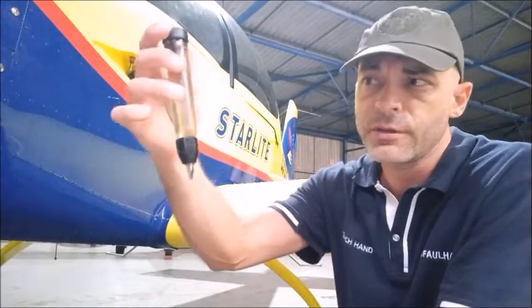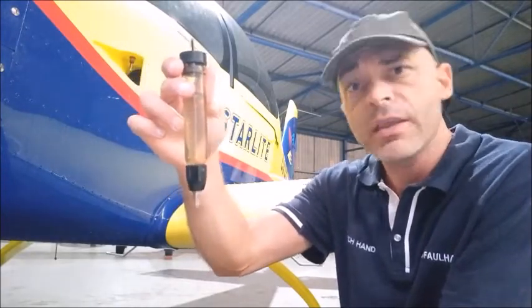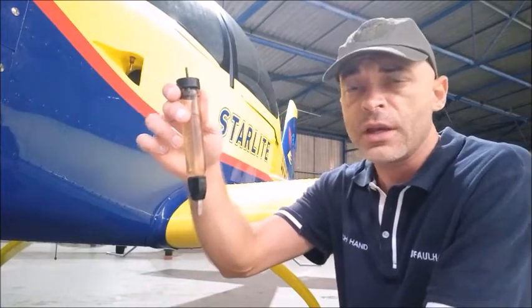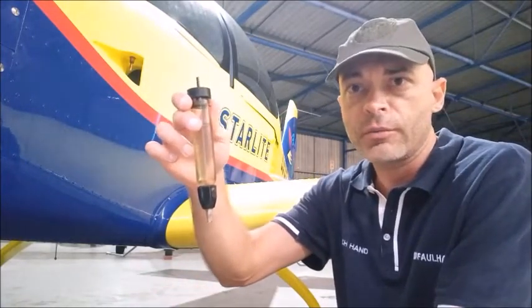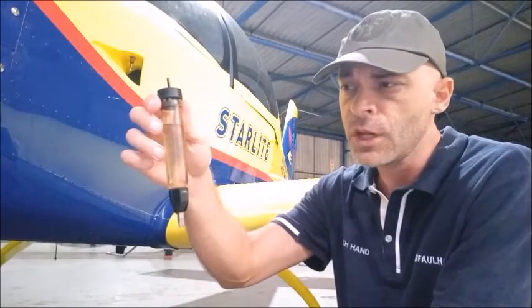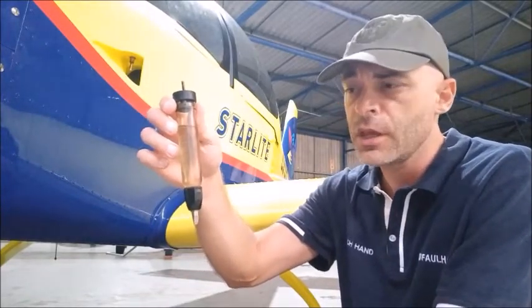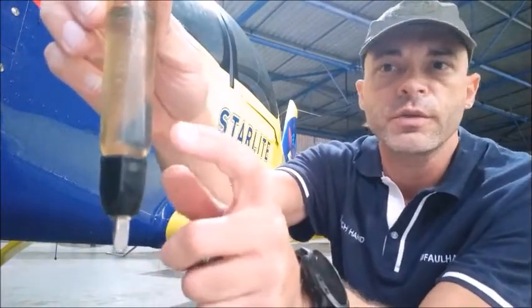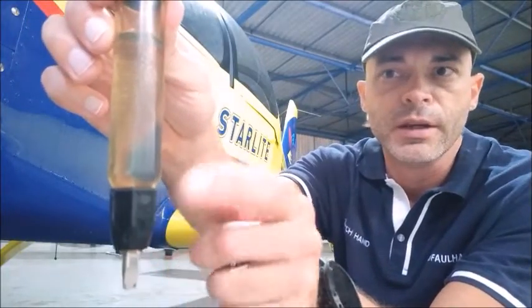So this is the color of the petrol that you can see over there. Other aircraft will use what's known as AvGas or aviation gas, and it has a different octane compared to MoGas. MoGas stands for motor gas. Essentially what we do is we look at the strainer and try to see at the bottom whether there is any water.